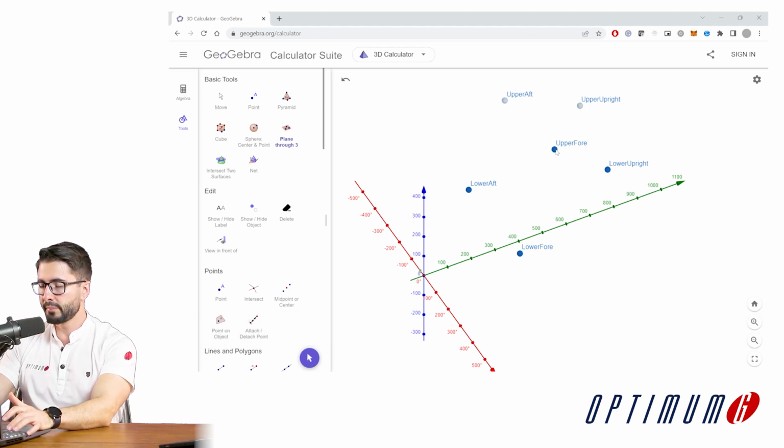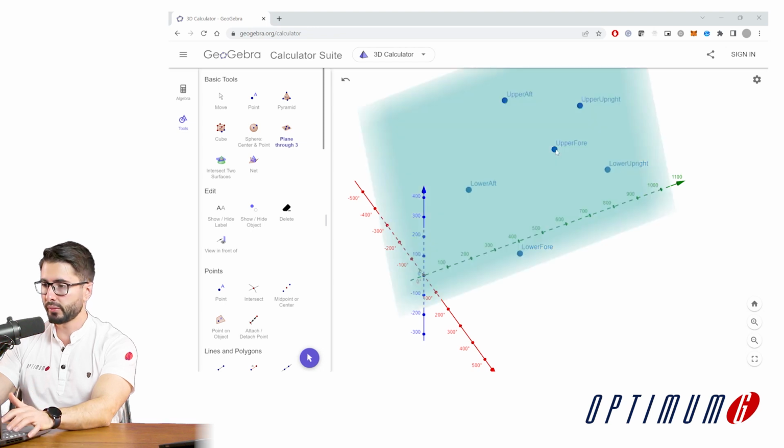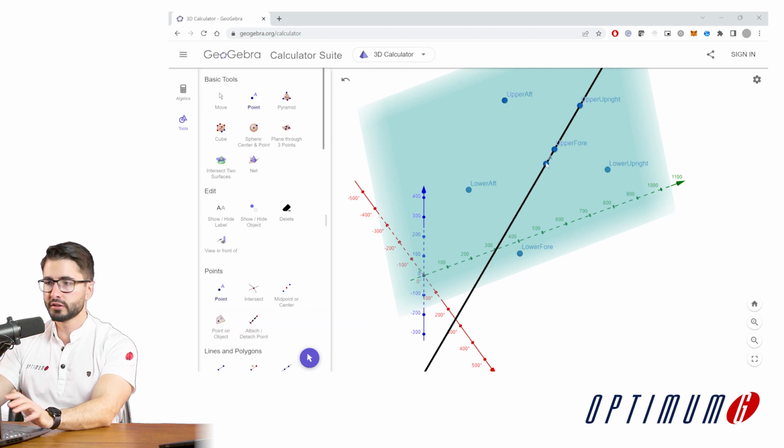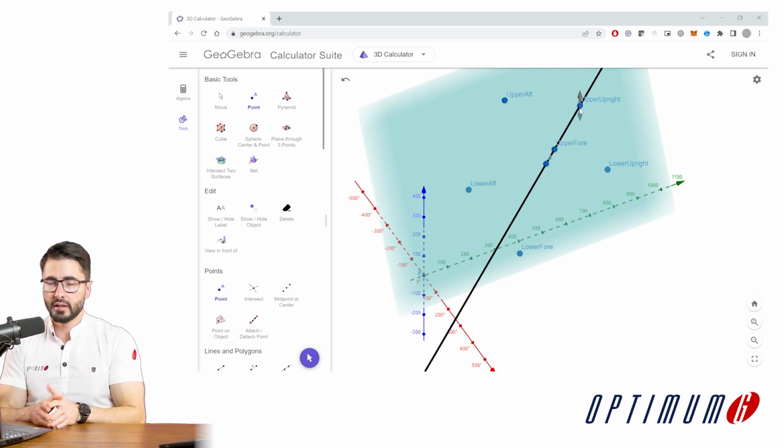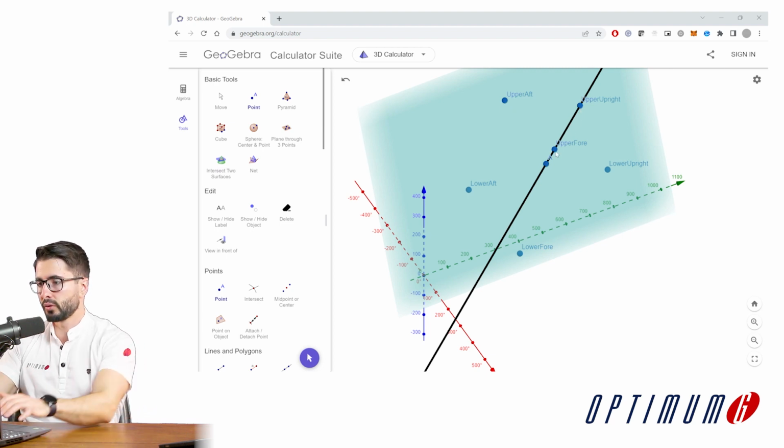So if I select the 3 pickup points, we know that 3 points define a plane. Now I have to find the new pickup points within this plane. In the case that we have to change the Y coordinate of both wishbones to be the same, upper and bottom, it can be a good idea that we use a line and we define a new pickup point in this line. This ensures that the angle of the wishbone is not tighter than before. So it is something that we might want to do.